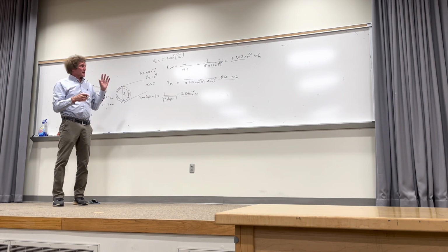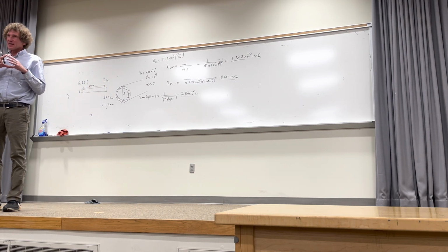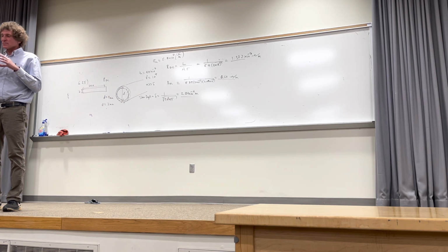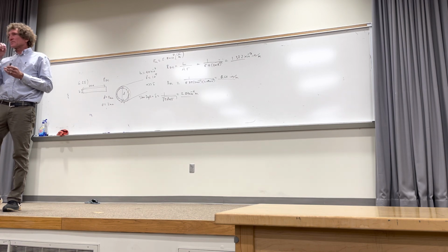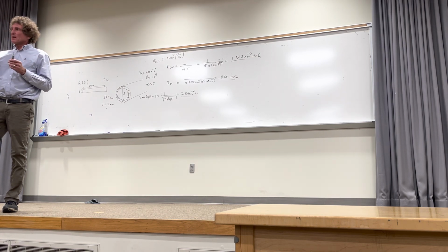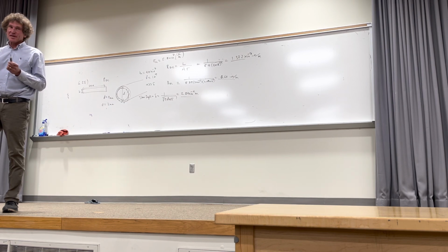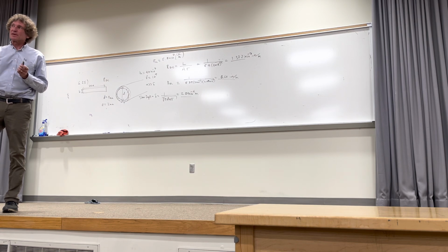Now, the first time I really saw how this affected designs, I was a grad student and I was doing work on a plasma etching system. And it was at 13.56 megahertz, which is a low frequency. But even at that frequency, the piping used to connect the power to the actual reactor was hollow. It was hollow. But they could use that to run a coolant through it.